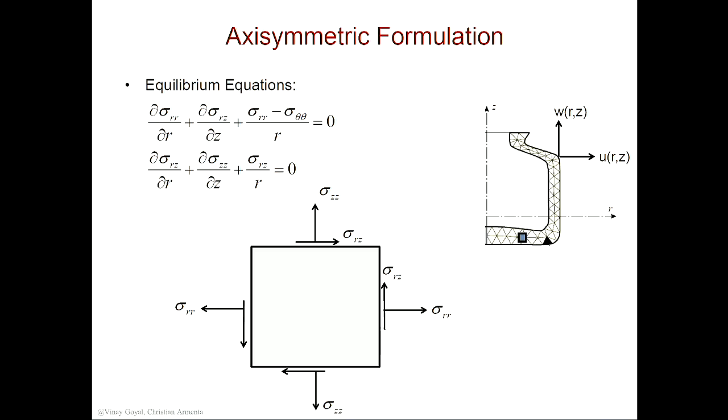So we're going to make a problem like that. You can do it by hand, and you will get PR over 2T. You'll get PR over T, and then you can compare against your hand calculations and Abaqus. So we'll do it that way. It's a good, simple problem for axisymmetric modeling.